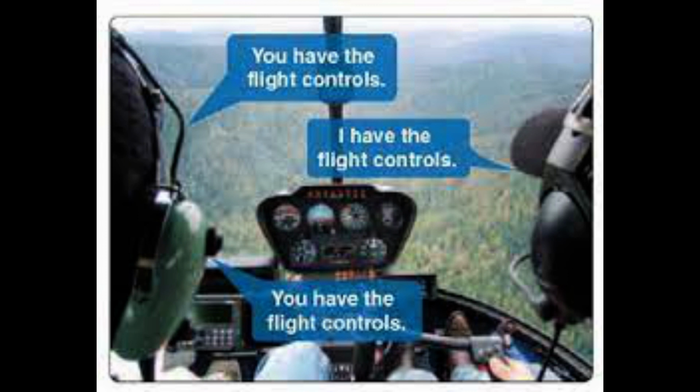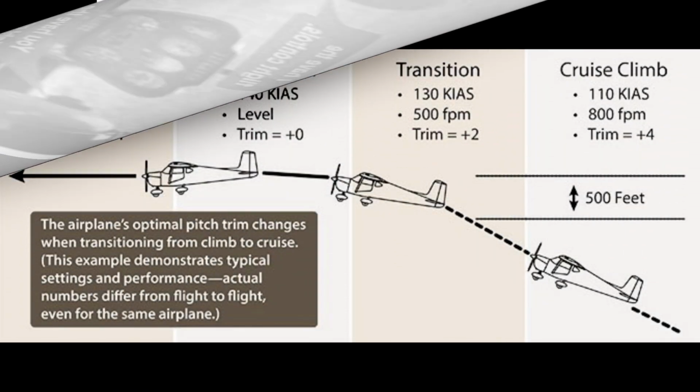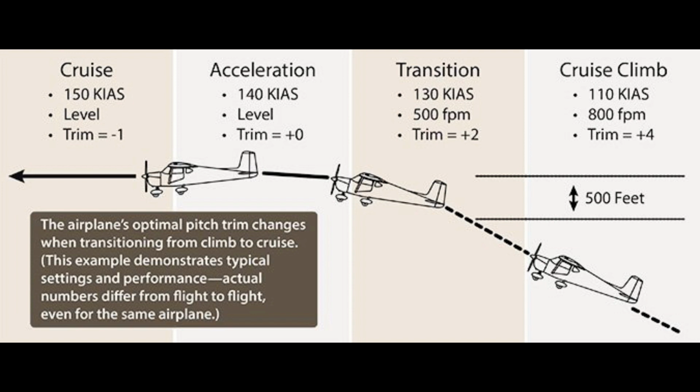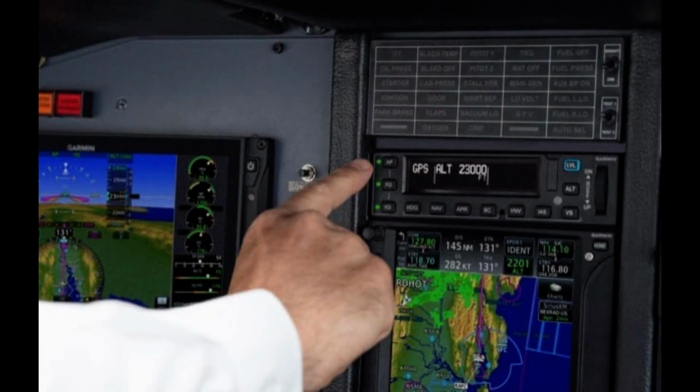Autopilot and electric trim system failures. It is vital that you become immediately familiar with the procedures required to disconnect or disable the electric trim and autopilot systems. Electric trim and autopilot failures can occur in the form of failure indications, unusual, unexpected, or missing actions, or, in the extreme case, a runaway servo actuator in the autopilot or trim system.